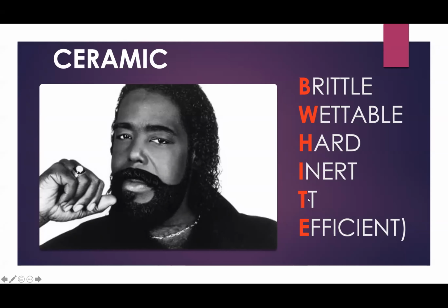So its use is it's great as a bearing surface. But the downside is it's brittle. And also you get this thing called squeak. Squeak is a problem mainly with the newer ceramics where fracture is not really a big problem. And it's defined as a high-pitched sound which is audible to the human ear. And it occurs in mid-range movements, while weight bearing, such as simulated stairs or climbs.